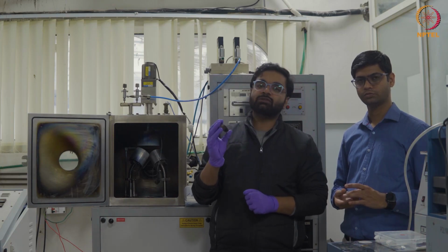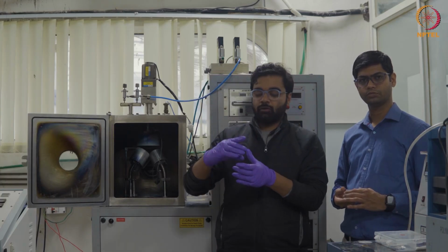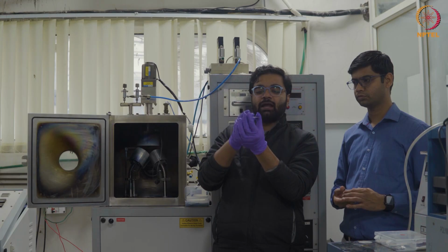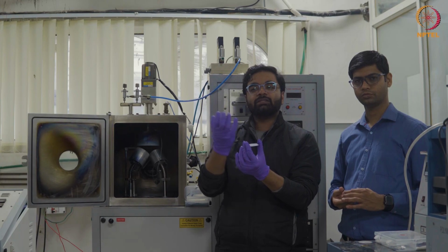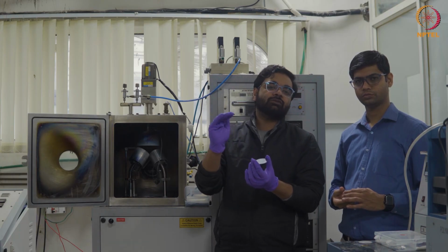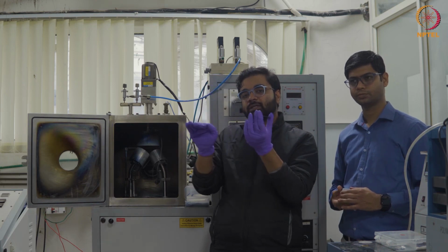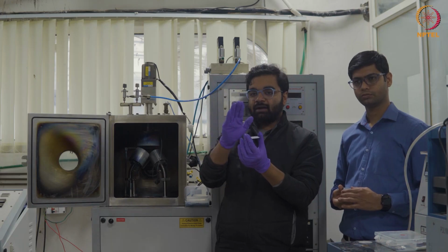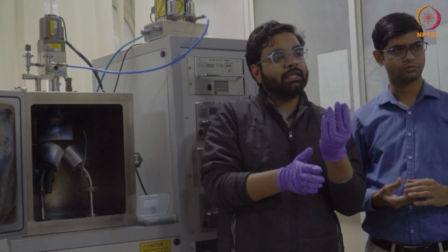Now this also requires optimization, because it does not mean that any thickness of PDMS will work for our case. As the laser falls from the back side and is transferred onto the second layer, the sacrificial layer, the laser energy is optimized so that the gas pressure is optimum enough to eject the material, because the laser energy should not interact with the third layer of the material. So we have to maintain that optimized thickness. Why? Because if the thickness is less, as the laser hits the surface, it will just tear off the sacrificial layer and interact with the material, which means the material property will get changed, which we do not want.